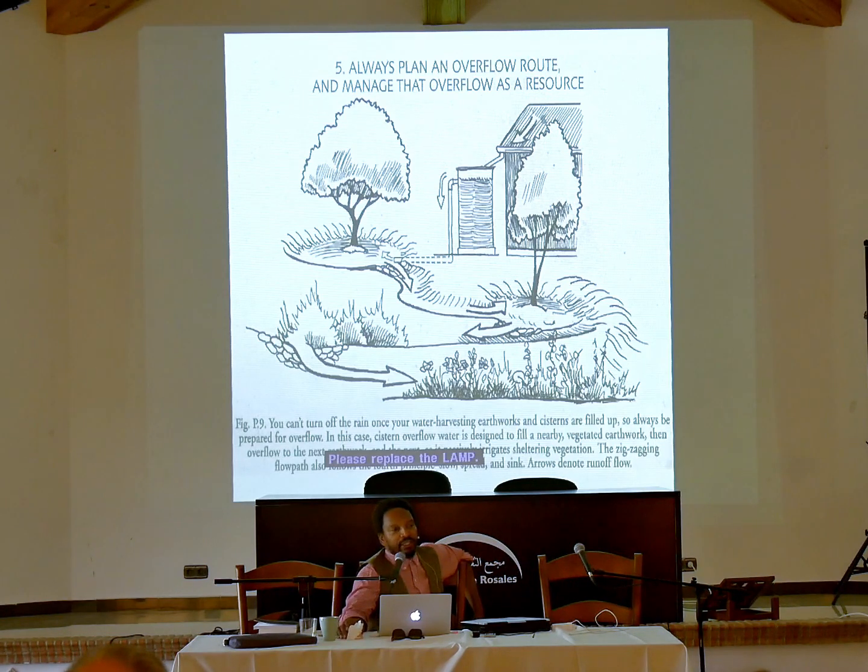But this is where having a bypass comes in. I mean, this is where the principle of over designing comes into play. Usually in engineering work, when you're designing something, you design for a factor of safety. So you'll over design it maybe to a factor of 2 or 3, meaning you're expecting to experience a load or stress that would be 2 or 3 times the load of normal usage.